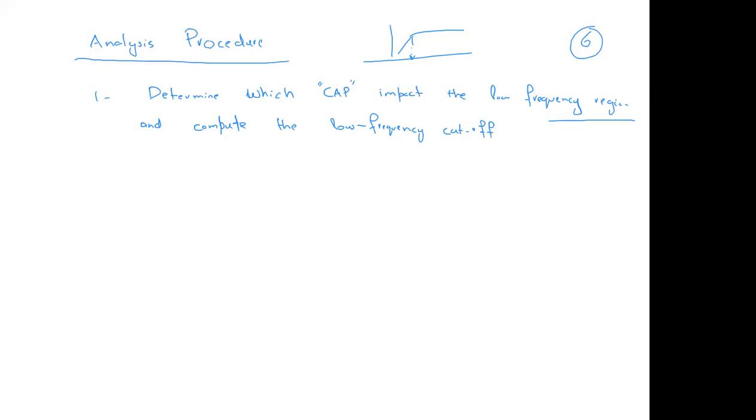That's very much important. For this analysis, we can neglect the parasitic capacitance. Parasitic capacitance, or your book is also using transistor capacitance, inherent capacitance. Transistor capacitance we can ignore because they are only going to impact the high frequency response. So that's the first thing. Second thing, calculate